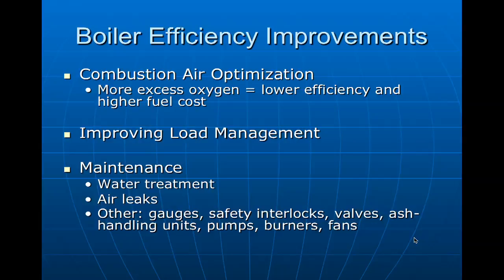Some ways that aren't improved here, well, it actually tells us by changing the oxygen content, we're going to be able to change the efficiency of it. I don't know if you've ever seen a chimney that's got really black smoke coming out of it. That means it doesn't have enough oxygen going into it. So what happens is I'm running in reduction there, and I'm lowering the efficiency, which means I have to use more fuel to get the thing to burn. So what I need to do is improve how I'm monitoring the air. So that's a big thing right there. If I can improve how I'm monitoring it, and then I can make changes to the amount of air that's in the system, I can make the thing burn far more efficiently.